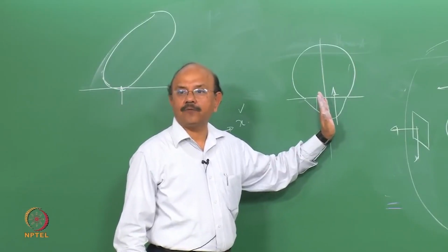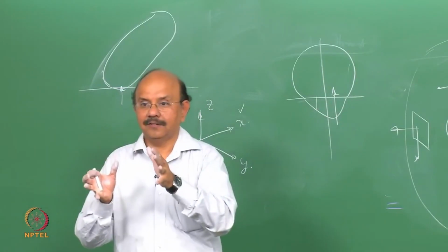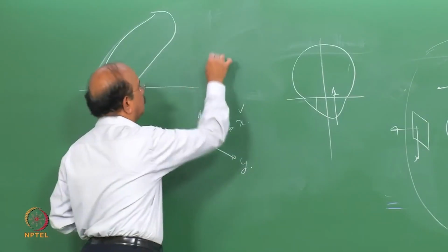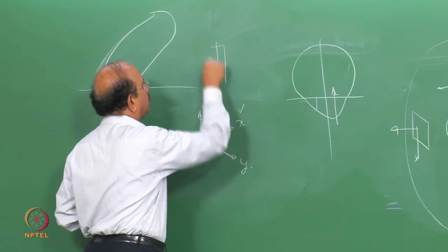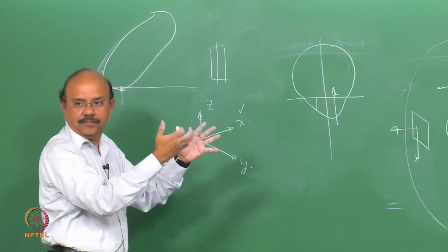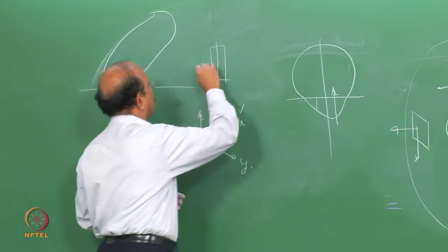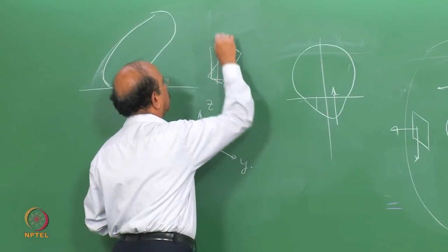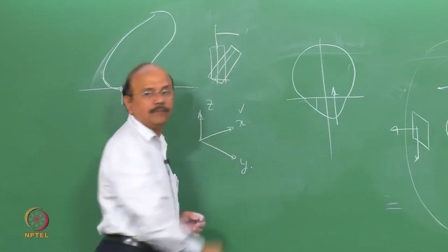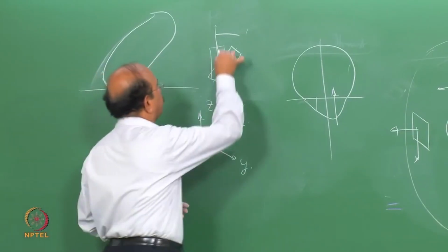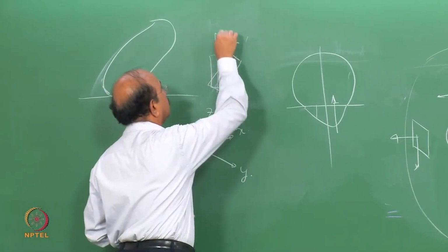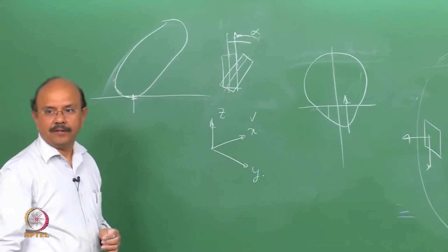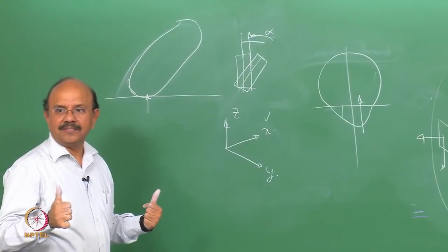Remember that we had what is called an aligning torque. If it's a plan view, a vehicle which is going straight had to take a turn, and so we gave a steering angle, and that produced what is called the slip angle alpha, in order that we get the centripetal force.